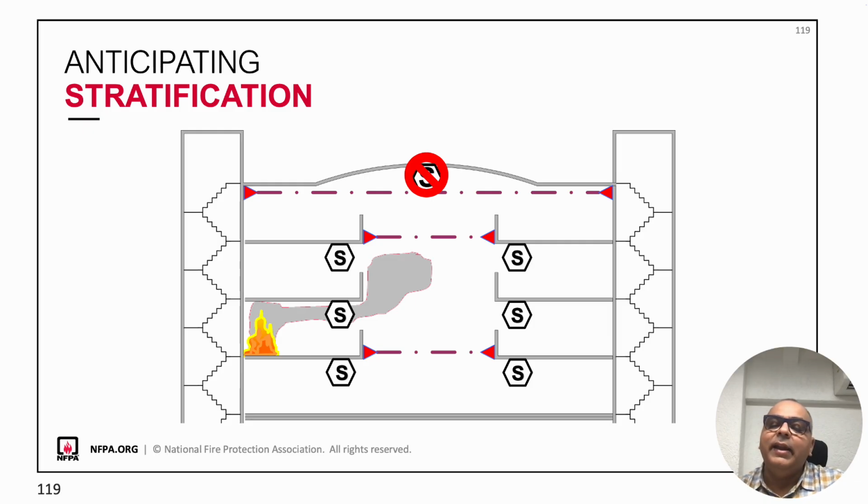Stratification can occur at any height, not only near ceilings. Smoke may remain trapped in the thermal balance layer of the floor. Detection must be placed within the smoke layer and not above it. Detectors on unaffected floors will not trigger in time.